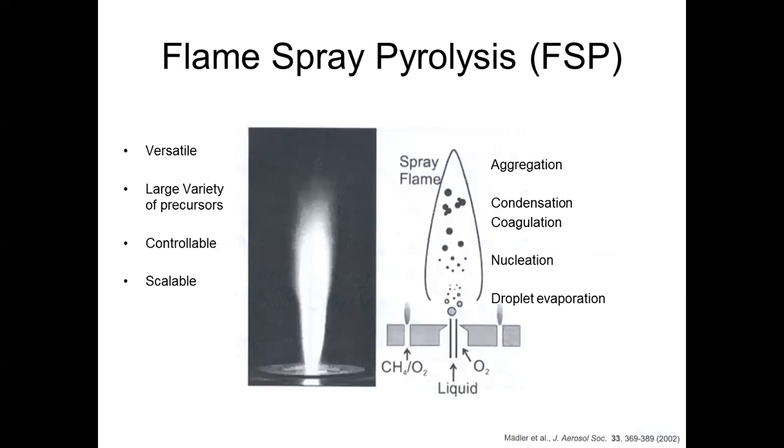So the more durable products come earlier in the flame. At the end of the flame is where we would get multiple particles put together, and they would tend to be weak, with a wider Gaussian distribution of particle sizes. Something we're going to get to in the presentation is how we would truncate the flame and control it. This middle area is probably where we would get the most robust nanoparticles and the particles with the smallest Gaussian distribution, and certainly that's desirable.